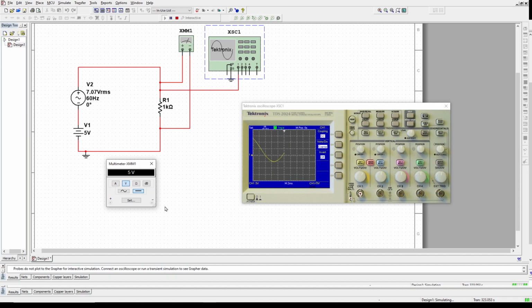And the AC RMS value, if we ignore that, is 7.07 volts RMS, which would be the case if we had a 20 volts peak to peak sinusoidal waveform. Okay, I hope it kind of clears it up. Try to recreate this thing, because I know you're going to be using Multisim, so hopefully this helps you with other subjects as well.